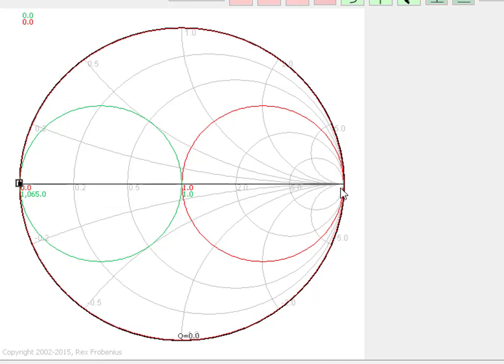And in terms of terminations, a zero impedance termination is a short. So the short is always going to be on the left. And I will have to keep my left and right straightened out. That's maybe also an important thing to keep in general, your left and your right. Same goes for counterclockwise and clockwise, by the way. So on the left, we have a short, and the terminations increase. At the center of the chart, we have the characteristic impedance of our system.